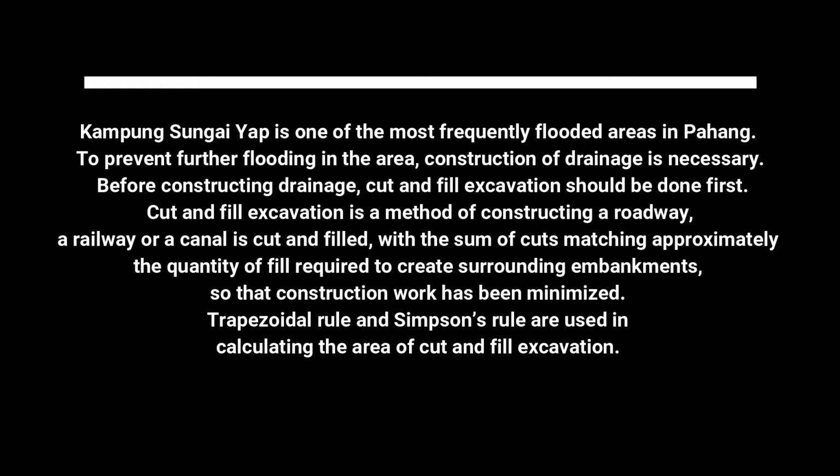Cut and fill excavation is a method of constructing a roadway, a railway, or a canal in cut and fill, with the sum of cuts matching approximately the quantity of fill required to create surrounding embankments, so that construction work has been minimized. Trapezoidal rule and Simpson's rule are used in calculating the area of cut and fill excavation.